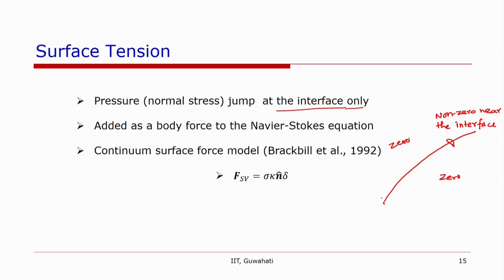And in these methods, one needs to appreciate the fact that the interface in reality is of almost 0 thickness. However, the interface is fairly thick in several other cases. In reality the interface is thin, but in the computational methods, it is at least one cell or one element thick because it is being discretized. So, the interface is what is called diffused.